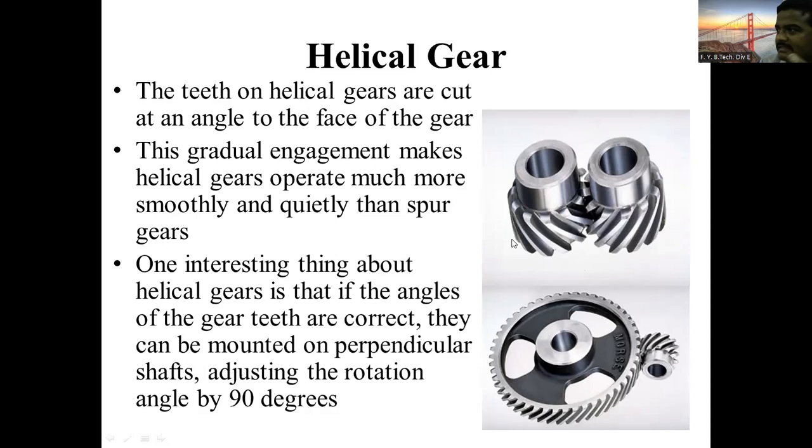This is what helix is. Helix angle is given. Angle is given to these teeth. That's why it is called helical gear. Now this helical gear is used for transmitting a large amount of power. Whenever you want to transmit a large amount of power, because it performs very smooth and silent operation.